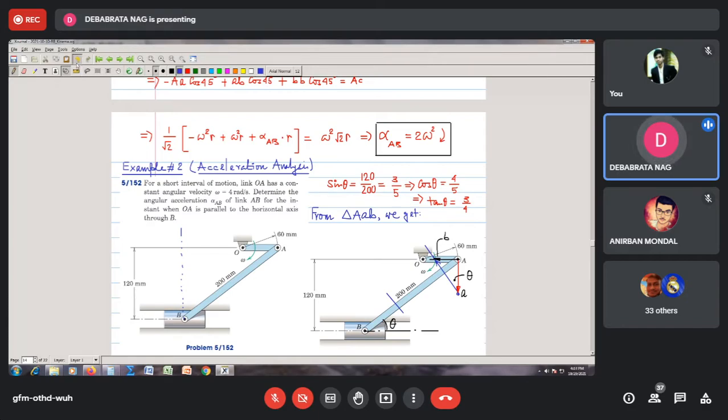All these things you will learn in kinematics of machines and mechanisms in your next sem, I believe. So I am not going into detailed discussion of that. Again, it is a degenerated 4-bar linkage. This is the driving crank, and this is the slider, or you can say it is a piston. It can also be called a crank connecting rod mechanism in the case of cars.